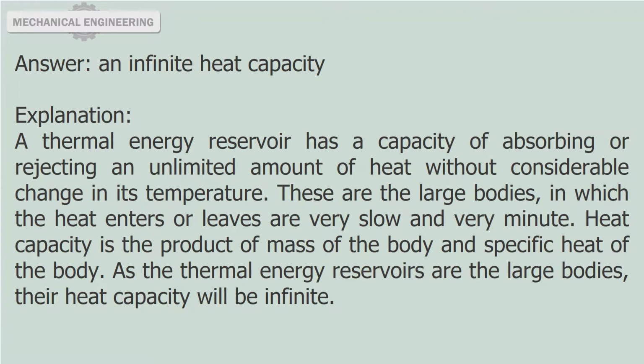Explanation. A thermal energy reservoir has a capacity of absorbing or rejecting an unlimited amount of heat without considerable change in its temperature. These are the large bodies, in which the heat enters or leaves very slowly and in very minute amounts. Heat capacity is the product of mass of the body and specific heat of the body. As the thermal energy reservoirs are the large bodies, their heat capacity will be infinite.